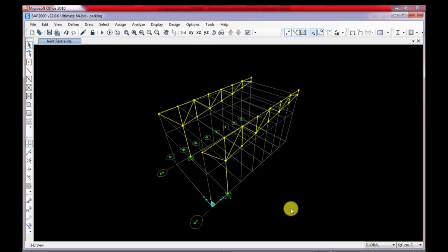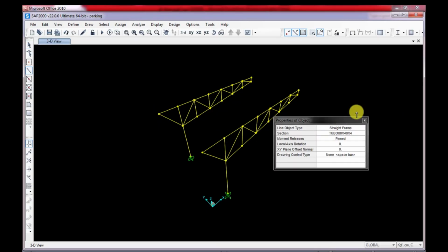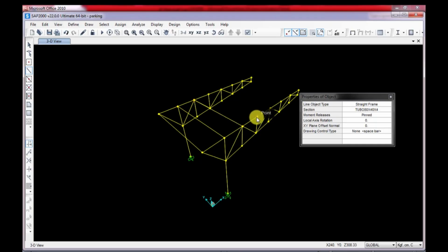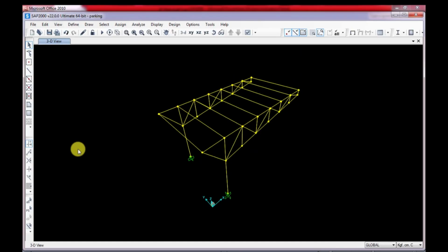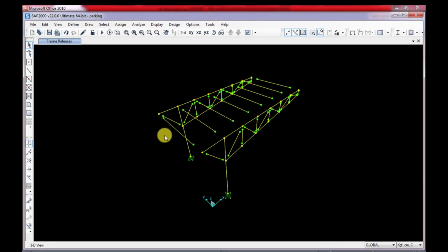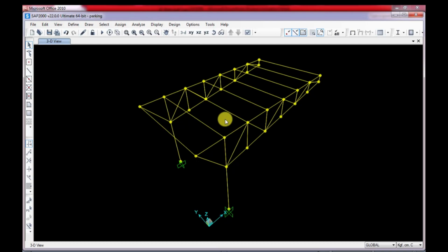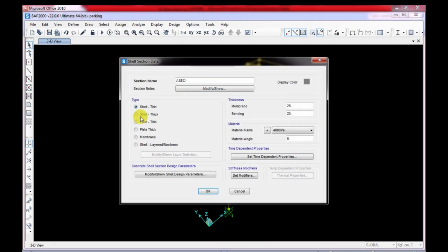After that, draw the diagonal members using the 80-40 box section to complete the truss web system. Once the truss is complete, assign pinned connections to the internal members if needed. Now, select the entire truss and replicate it in the Y direction. Distance equals 300 centimeters. This creates the second parallel truss. Next, draw the horizontal members, the purlins, between the two trusses. You can use the 80/40 box section for these elements.